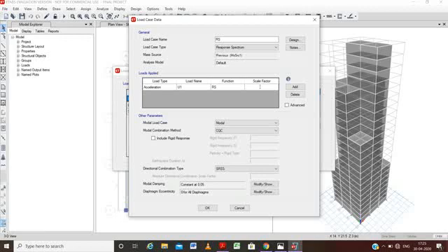As we perform this, we will get a value that is 16.335, because here I, the importance factor, is 1.5, the gravity acceleration is taken as 981 mm per second square, and the response reduction factor, as we have earlier discussed, was 3. So we will get a value 16.335, and we will add this,